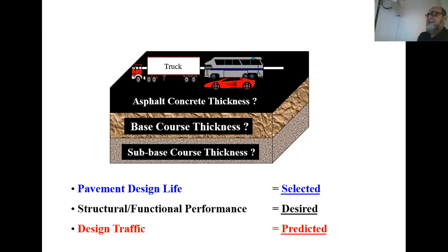And if you are designing a geometry, then obviously sometimes the trucks may be considered for turning radii, but if you are designing a local road, then you consider a car as your design vehicle. The difference between geometric design and pavement design is that the design vehicle is different. For the pavement design, it is always a truck, but for the geometric design, it can be a truck or a car, depending upon the purpose of the road.